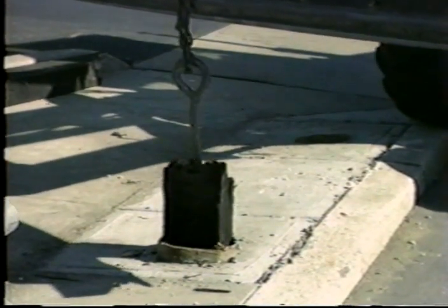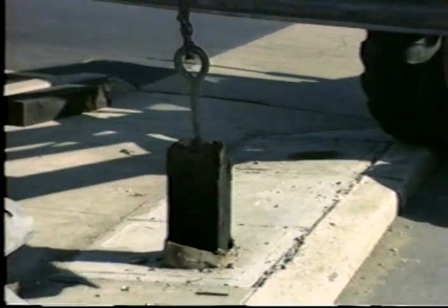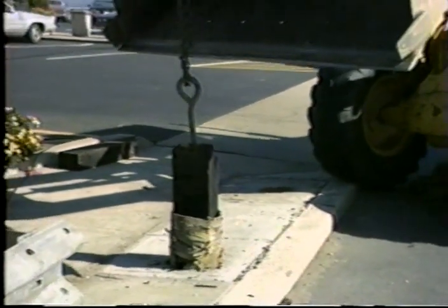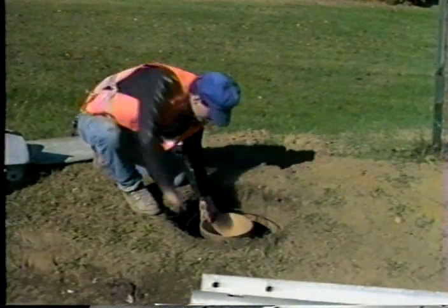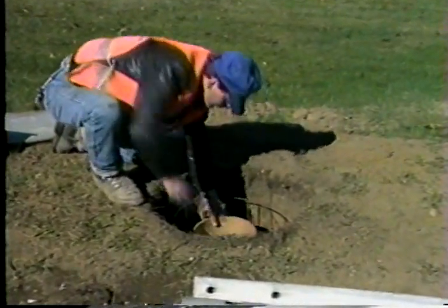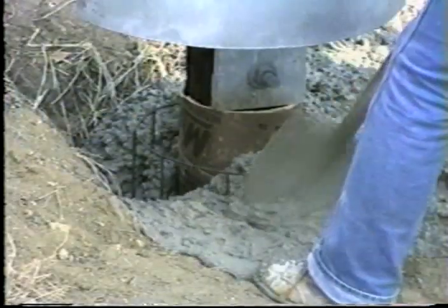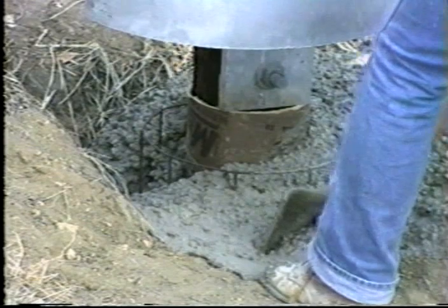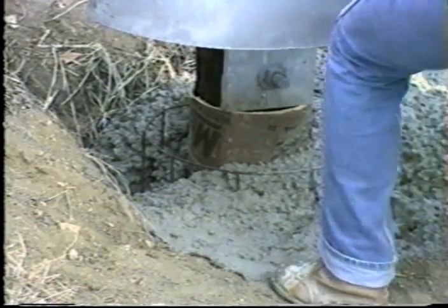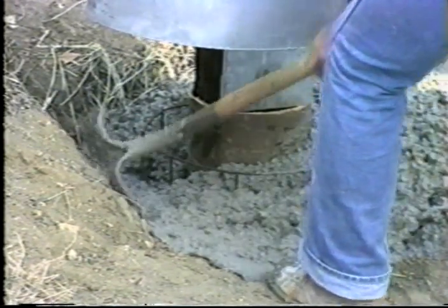A styrofoam sleeve and a steel sleeve with soil plates are 2 different concepts available. Another solution has been to place a heavy pressed paper tube around the post when it's installed. The footing is poured around the outside of the tube. Now, care must be taken to ensure that no concrete is placed between the tube and the post.